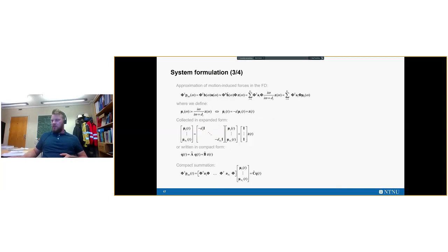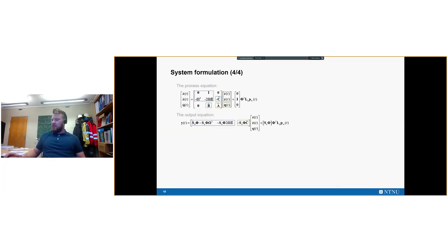And I think we will not go through the details in this slide, but rather what we end up with is a very compact model that has two parts. The first part is a reduced order model for the contributions from the structure, the buoyancy, and the mass at the infinity frequency. And secondly, we have a subsystem that describes the hydrodynamic mass and damping. And we also have some coupling terms that describe the interaction between these systems.